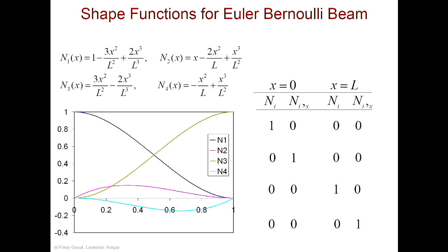Just wondering, do these shape functions have to satisfy the requirement of having a complete polynomial, like basis functions have to? Yeah, they're complete. They're linearly independent. And they satisfy the Kronecker delta property as shown here. Do you have a question? So I'm wondering why would N1 be complete? Wouldn't N1 not be complete? Wouldn't it be missing an x?